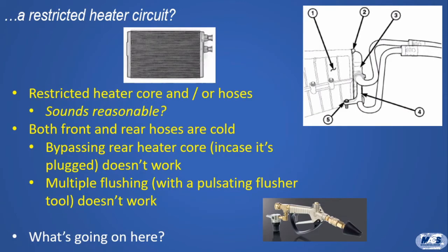Well, how about a restriction in the heater circuit? That seems like a reasonable thought. The technician finds that both hoses to the rear heater are cold, and so he disconnects them from the core and connects them together to bypass the rear heater altogether, in case that was plugged. But there was no improvement. However, he flushes the rear heater core and reconnects the hoses to see if that has any effect, which it doesn't.